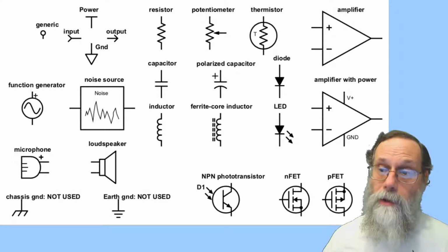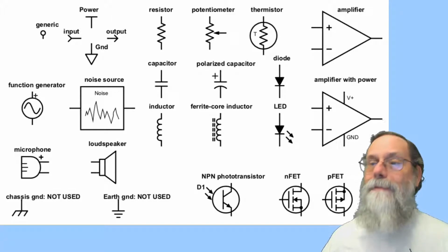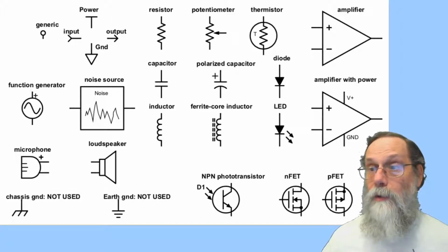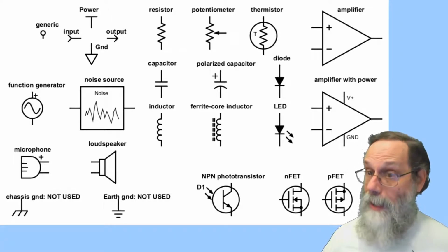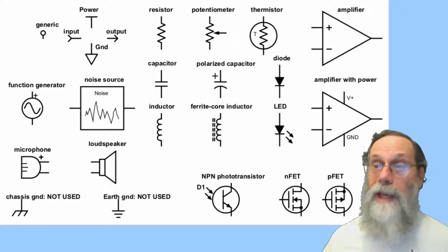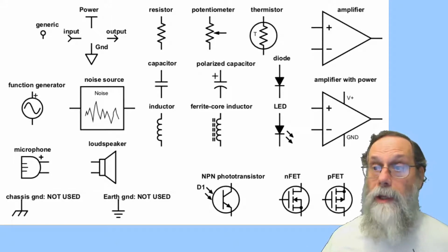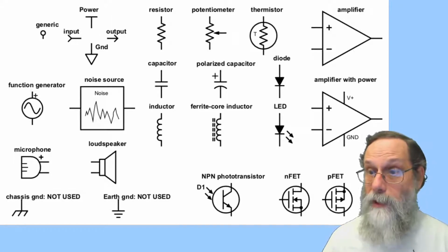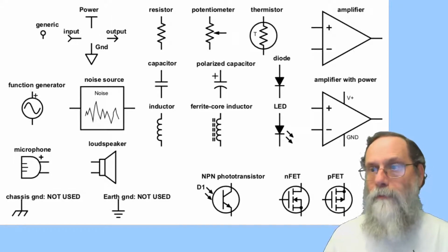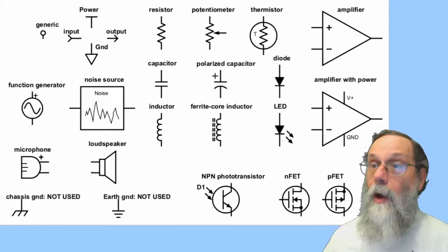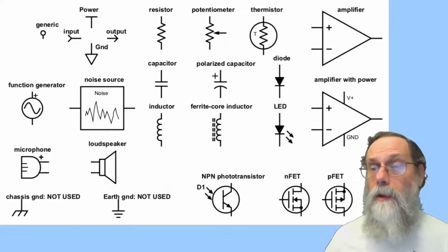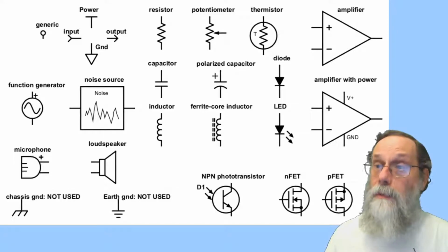If you do decide to put it into your schematic, then the function generator has two connections to it. Make sure they're both connected, because anything that's not connected on a schematic diagram indicates a problem. Either the schematic diagram was never finished because you've got this wire that's not connected to anything, or sometimes there's something that's deliberately not connected.